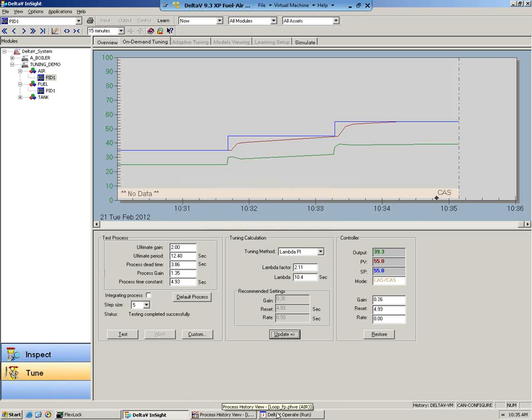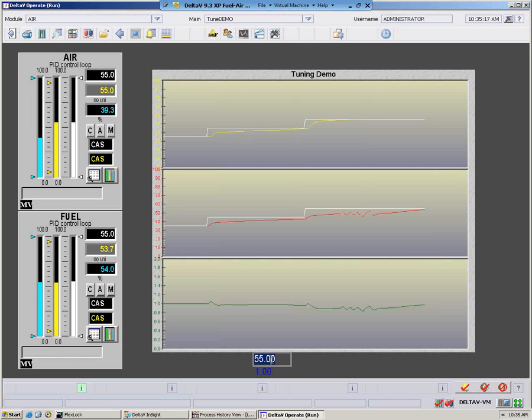room. Okay. So Kurt, have you updated both of them? Yes. And you're using lambda on both of them? And have you got them set for the same lambda time? Okay, so now they're set both for the same lambda time. So now as we do a bump test. Okay, so based on the earlier bump test we ran, now we should have them both at the same lambda time.